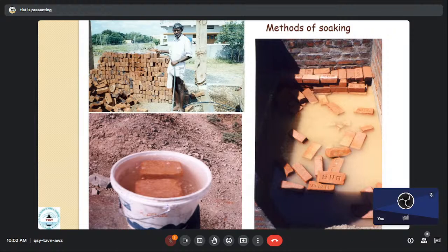You can see such an old person on the side who will always be pouring water like this. Can you just imagine what happens to the central brick over there? Will it get soft properly? If not, what is going to happen? If it is not getting soft or wetted properly, what is going to happen to this brick and the subsequent brick masonry? Any idea?